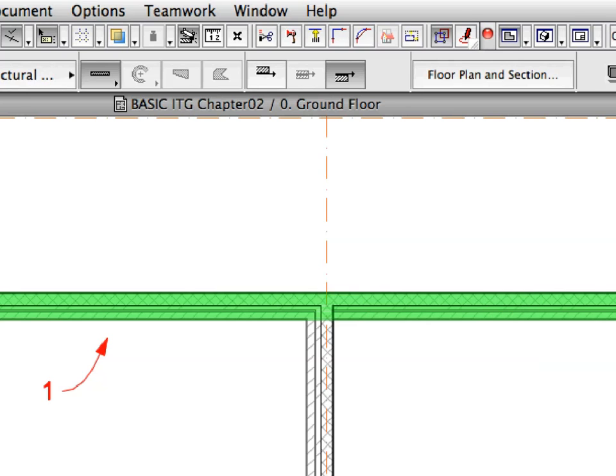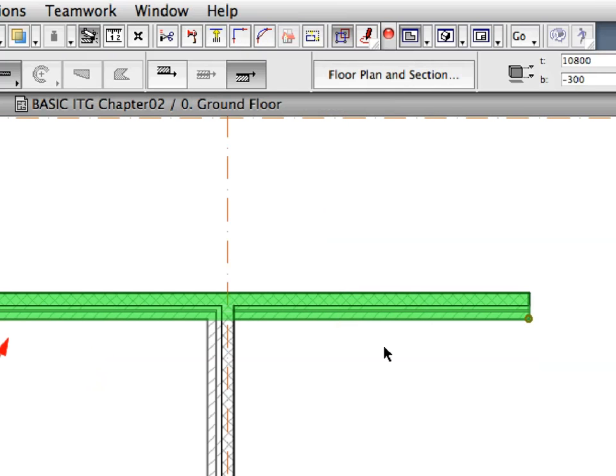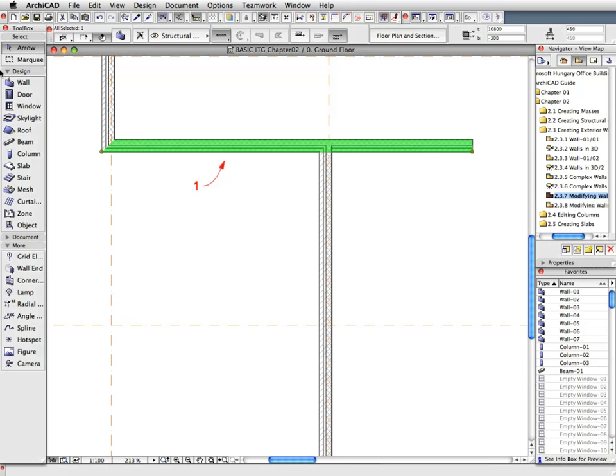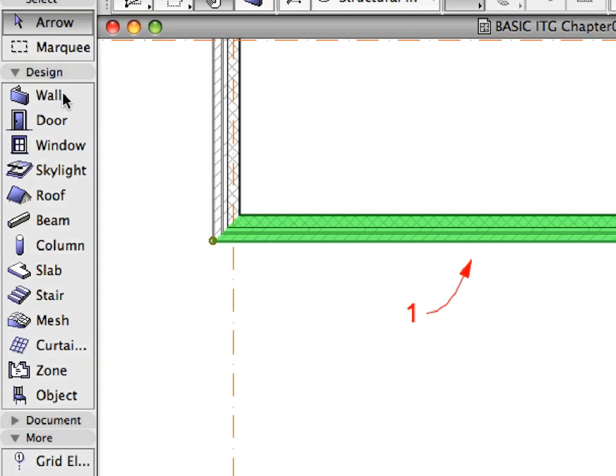Press the Enter key to accept this drag vector distance. The vector's angle will be 0.00 degrees since you have your cursor on the guideline. The length of the wall changes to the specified length. With the wall still selected, switch to the Wall tool in the toolbox.